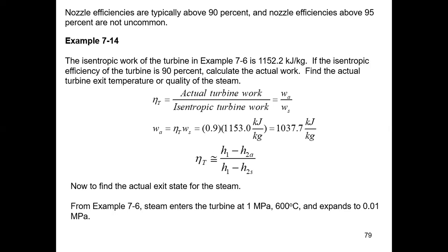And we know those things, so we multiply, so we get W adiabatic. And we also know eta of the turbine is given by H1 minus H2A, adiabatic, or actual, I meant to say actual, divided by H1 minus H2S. So WA is the work done actually. Actually turbine work.